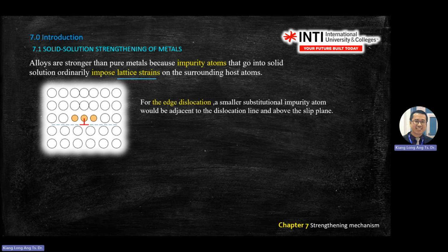If you use interstitial impurity, you need a lot more impurity compared to substitutional impurity. You can calculate the volume of this space, then from the table of elements, for example carbon, nickel, you have the radius. Maybe I'll give you the other parameters. You should be able to calculate how many atoms can be filled inside here.